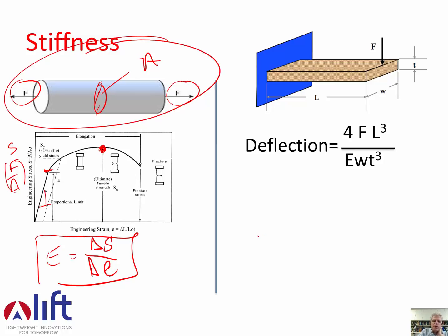But what is not so difficult to do is to take a regular old table and then take a cantilever beam, hold that on with a C-clamp like that, and you can put a little mass on this, and you can see that the thing will elastically deflect. And that elastic deflection depends on how stiff that material intrinsically is, what its Young's modulus is, E. So what you can do is set this up and measure the deflection.